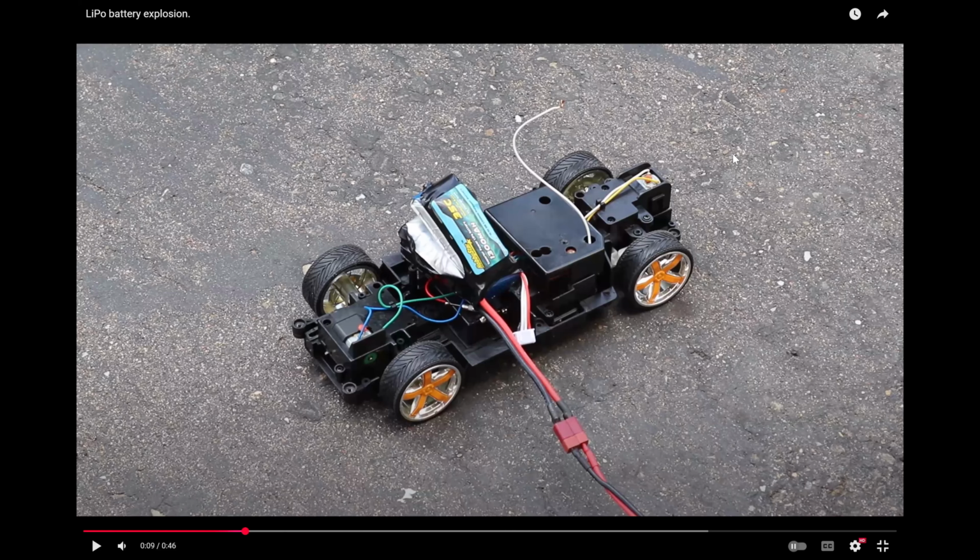If that happens, it's very difficult to put the fire out because it's a thermal runaway. The electrodes themselves have oxygen in them that they release. So even if you pour water on it, there's still oxygen from the electrodes, which are metal oxide electrodes. Another thing is, if the lithium polymer battery is more than one cell, the first cell may burn and the other two haven't gone off yet. So you may think it's gone, but then it'll flare up again. So it's very hard to put out.